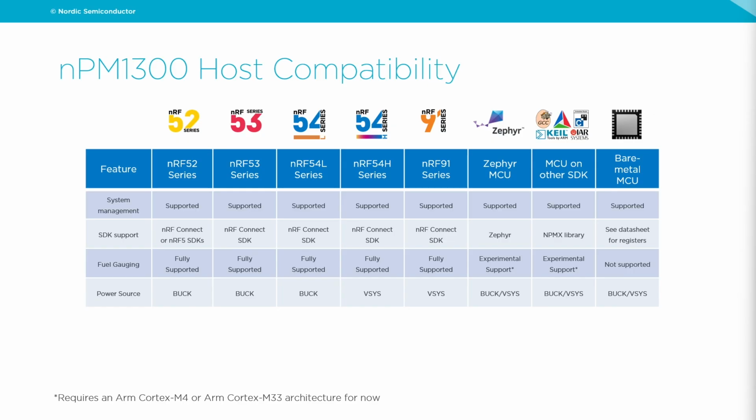If you have an nRF52 series working on the nRF5 SDK, this is also possible to use, but it's not recommended. For any Zephyr-based microcontroller, you can use Zephyr. Here you will have the same support as in nRF Connect SDK. For MCUs on any other SDKs, you will be using the NPM-X library, which is a part of our MDK, which is used when you are using the non-Zephyr SDKs. On a bare metal MCU, you can always look up in the data sheet which registers need to be set. So it's a manual process, but it is possible and it's usable.